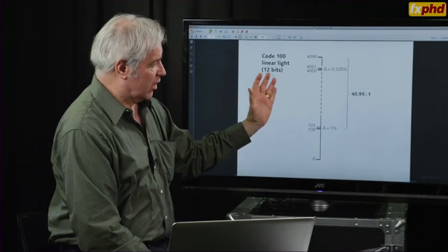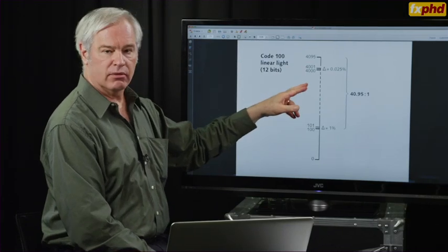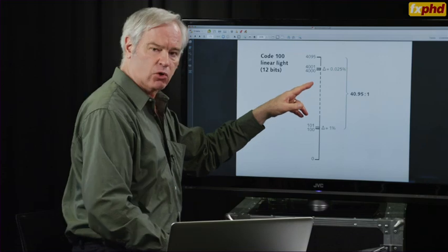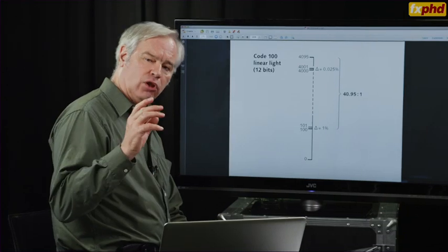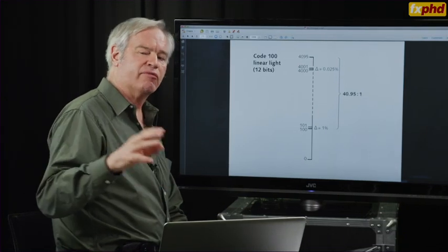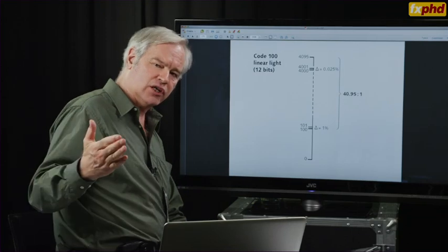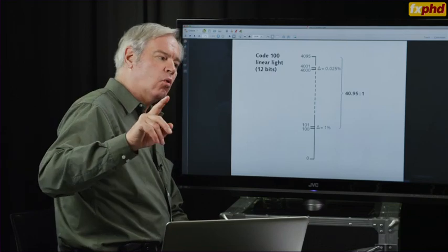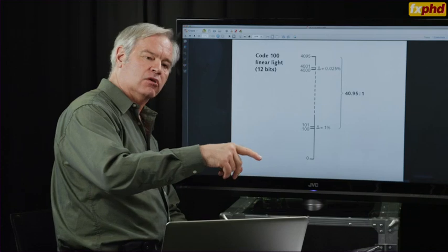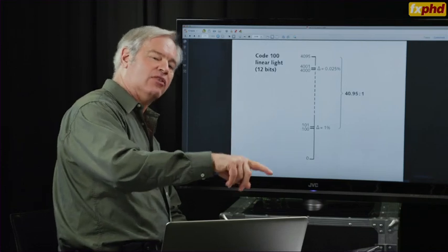The other way to overcome this bit depth issue, the fact that to record linear light requires a lot of bits, is to use logarithmic coding. And that's now fairly common for acquisition, and there are many different log forms. However, nobody has standardized an anti-log at the display.